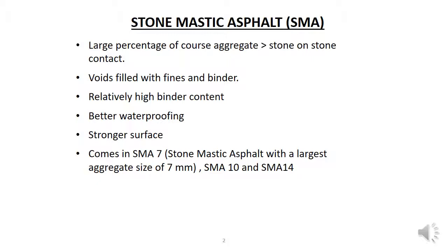Designing and laying an SMA takes more experience and skill than laying other asphalts, as it is very easy to get the proportions wrong and end up with too much binder on the surface, resulting in a loss of surface texture and loss of skid resistance, as well as having a surface that will wear away quickly. Too little compaction can result in air voids in the mix, which makes it permeable. The degree of skill required and the extra binder mean that SMA surfaces are more expensive and more difficult to construct, and so only justified for high traffic areas.